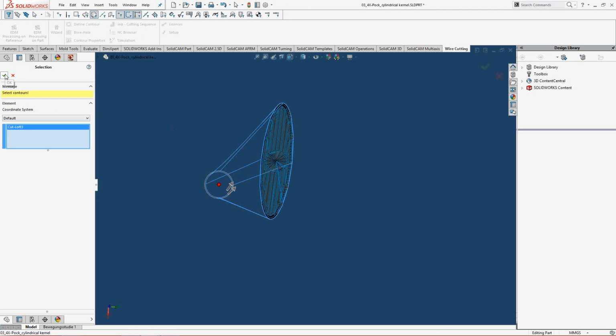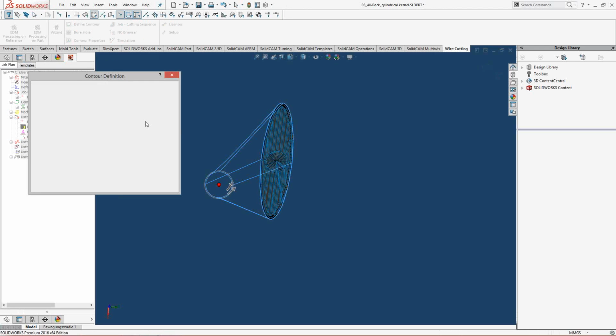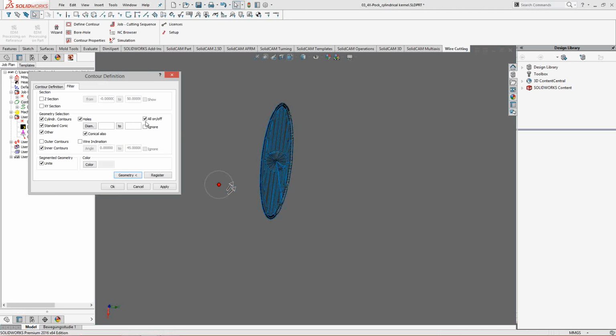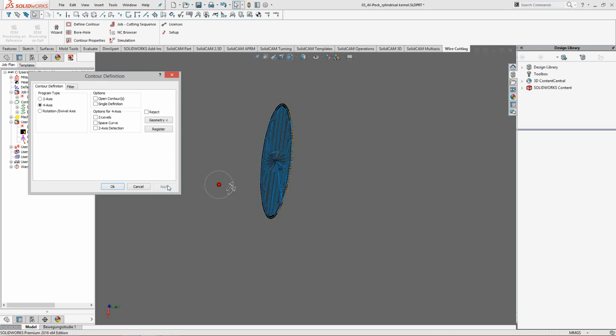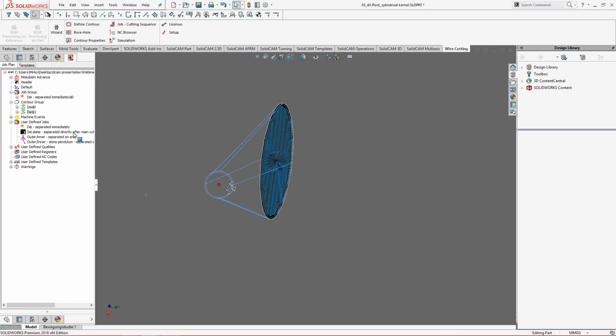Now the spiral algorithm allows us to not waste too much wire, because this strategy allows us to achieve much more contact between wire and your die, and therefore you will have nice cutting conditions and your wire will be 100% used. This is the purpose of this strategy.